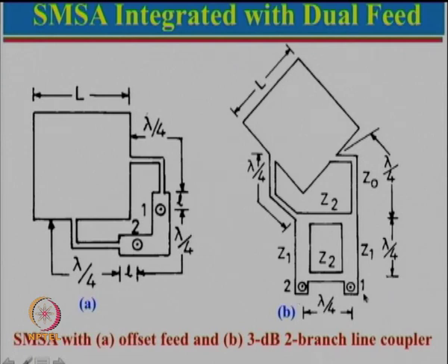Now, for this particular port here, actually speaking, nothing comes here, that all depends how we choose the impedances. So, in this case what happens? The path over here gives us 90 degree phase difference, and then this is 90 degree, another 90, another 90. So, that is 270 degree. 270 degree is also equivalent to, you can say, minus 90 degree.